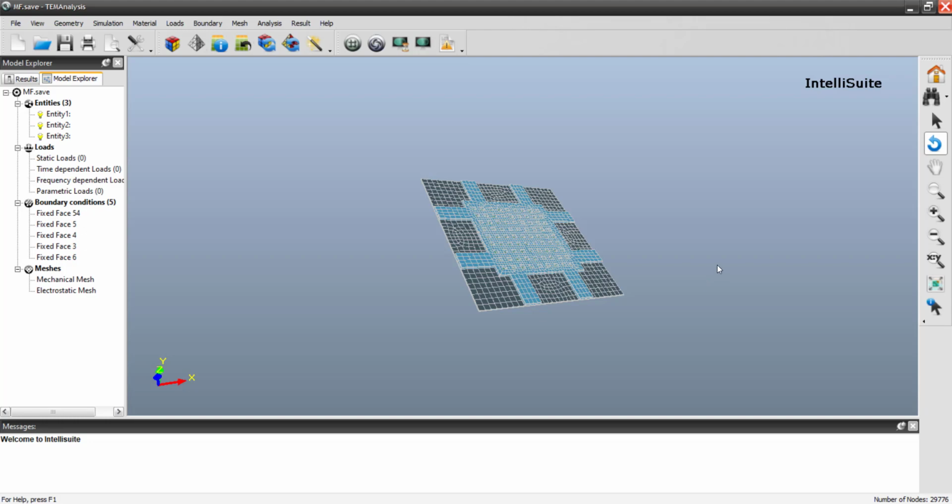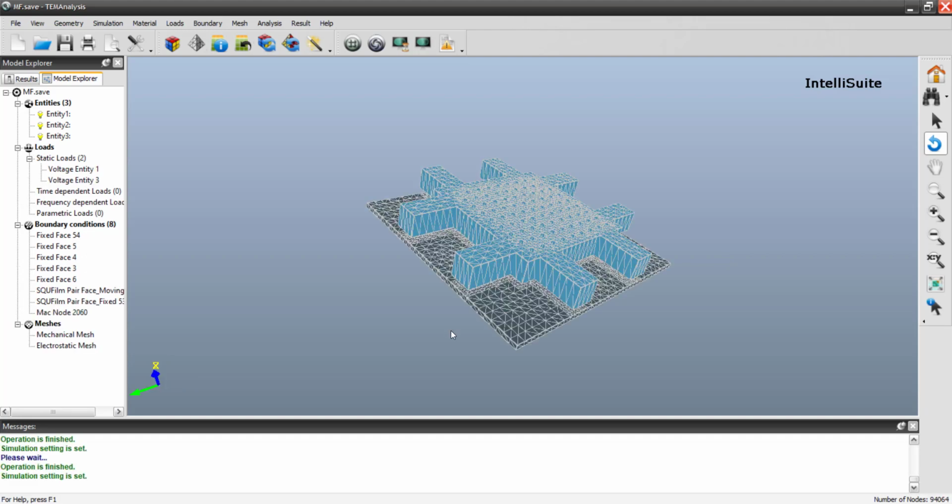So to incorporate all of those things, we will have to do a macro model simulation. This is essential because these damping factors are driven by the ambient conditions. Based on the ambient conditions, the damping gets decided: the squeeze film damping, viscous damping, thermal noise kind of stuff. So for that reason, we'll have to do a macro model simulation. So let's perform a macro model simulation here.